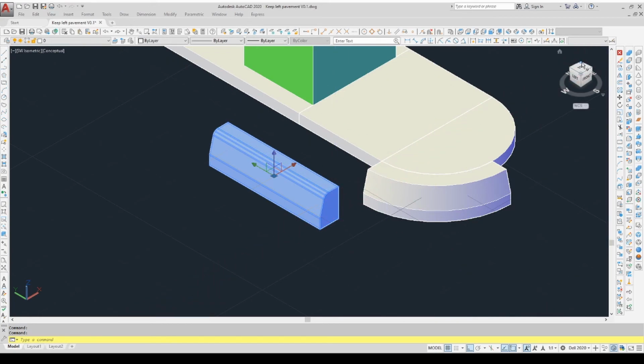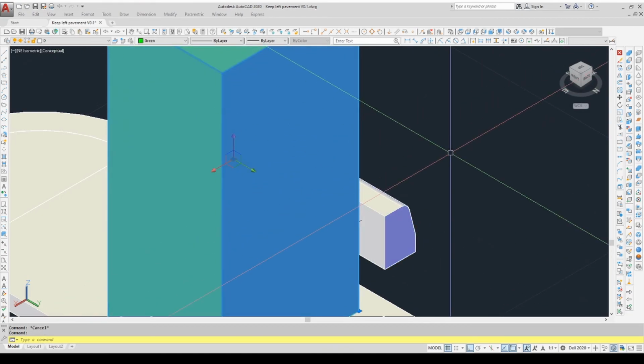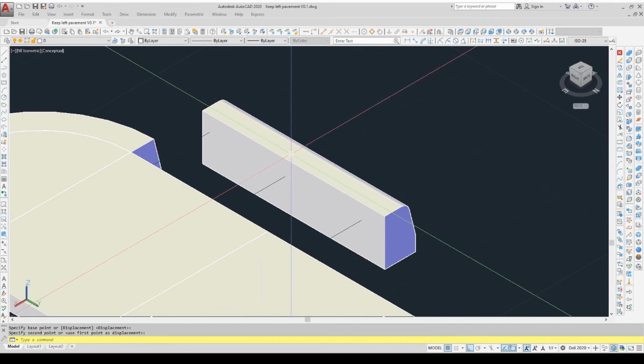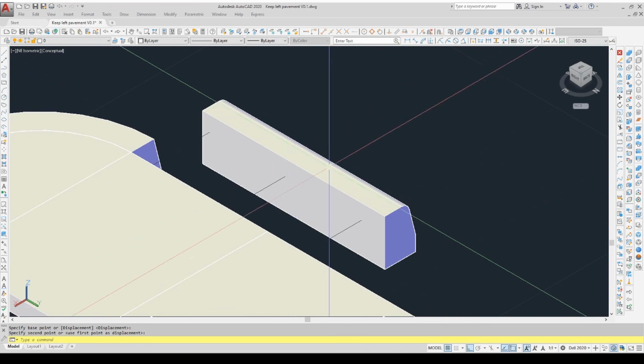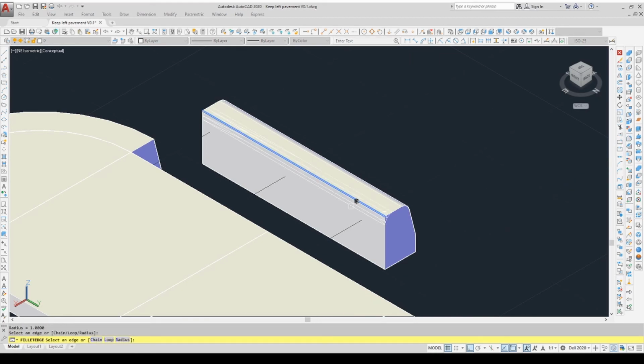So if I flip it round, hold on to your chairs. Oh, my bollard's in the way. So let's just move the bollard out the way for the minute because it's in the way of my working area. So now we can put in the chamfer on the back edge that's going to form our fillet or little gap between the two items. So I select chamfer again. I can select that edge, but that's too big. That's probably going to be too much.